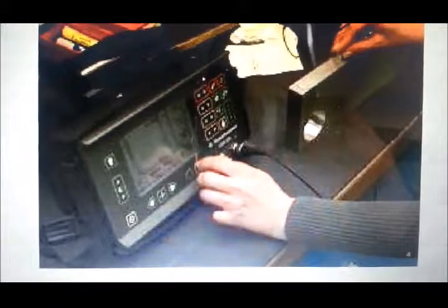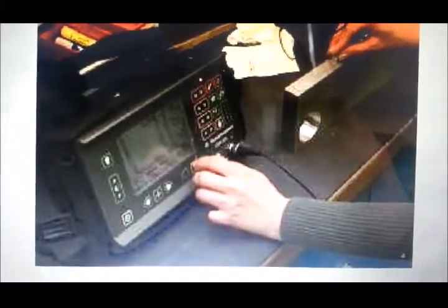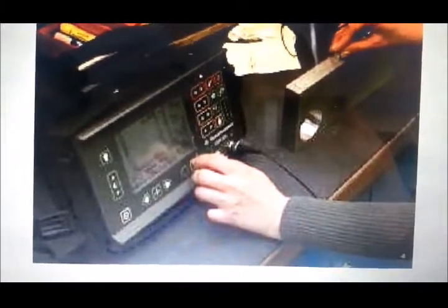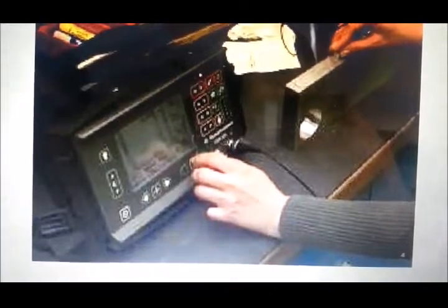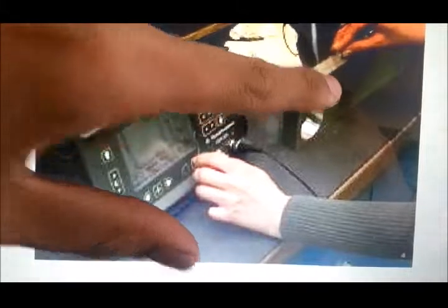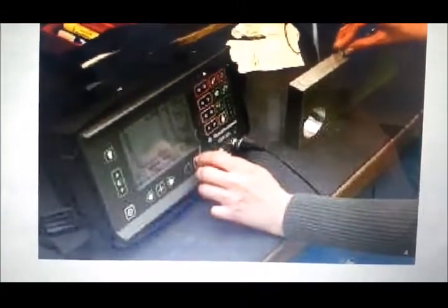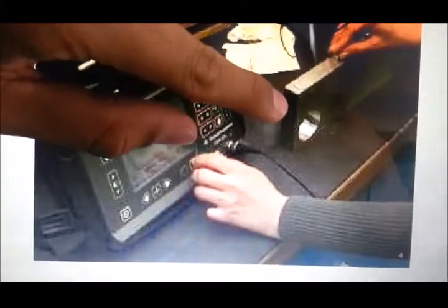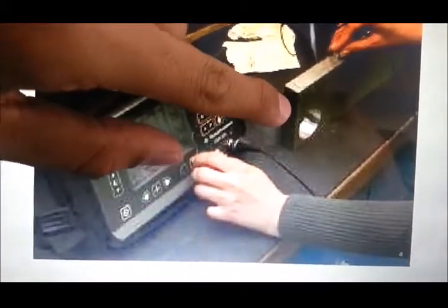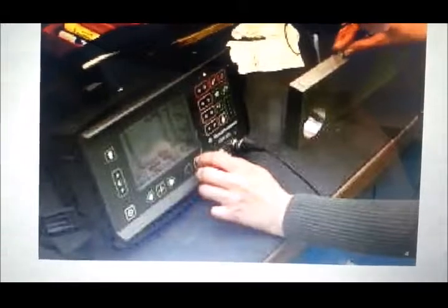When it's over 50%, we have to take the reading next to that, which will be our vertical distance from that probe to the invisible hole. When we get the vertical distance, we can calculate the horizontal distance from any edge of the aluminium piece. From this side, or we can calculate from that side.